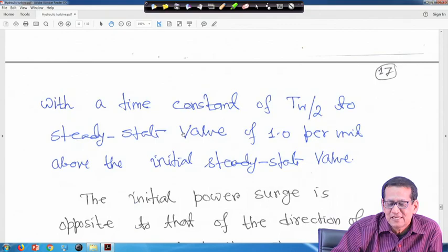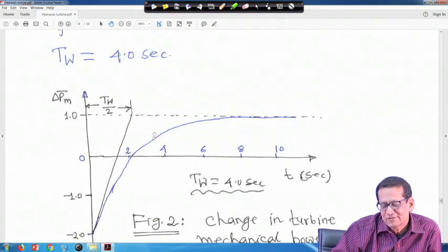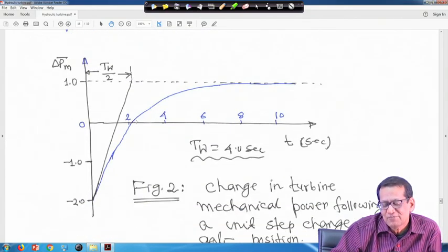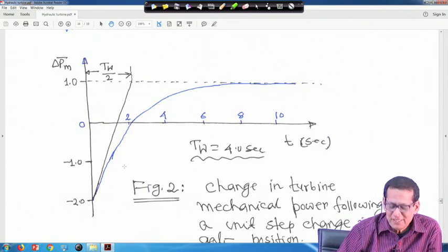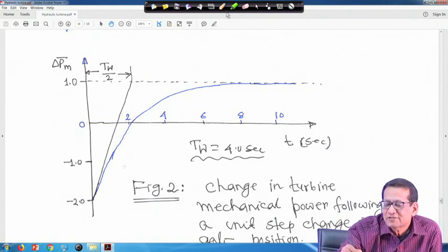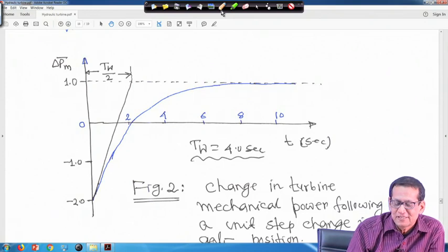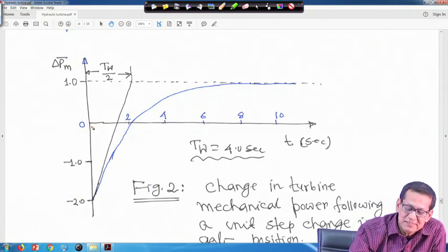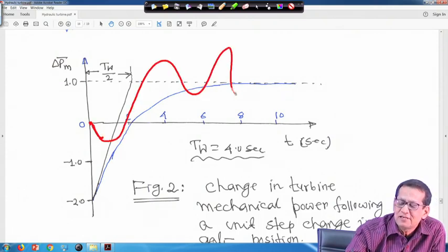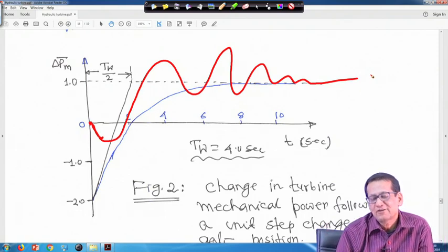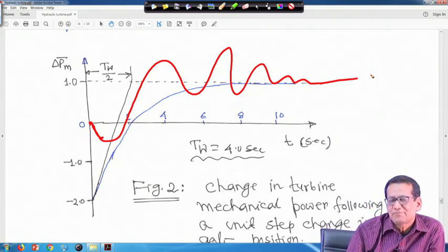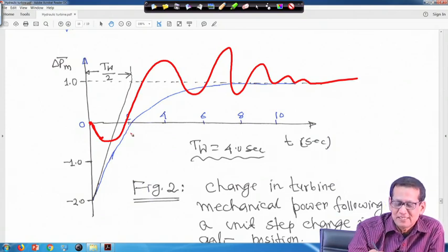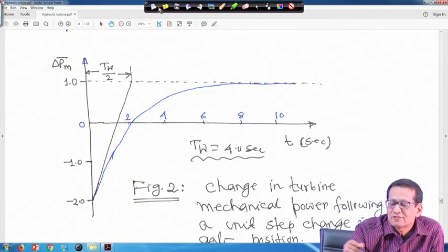So, that is the thing with this small turbine and this small example. When you connect it to the system, the governor is not considered, right. Initially, if you plot the generation for a hydro turbine, it will be like this, and finally it will settle something like this. Lot of oscillations will be there, but it is simply a first order model, governors are not considered. So, initially it will be like this, right.